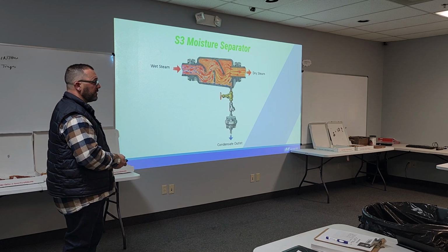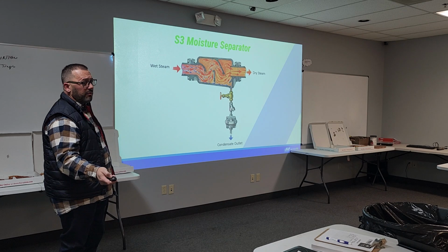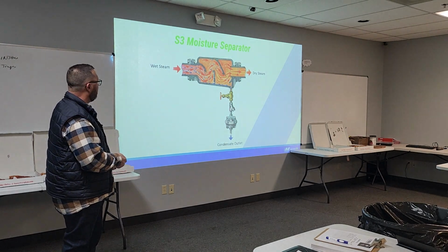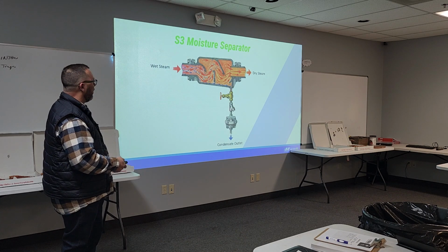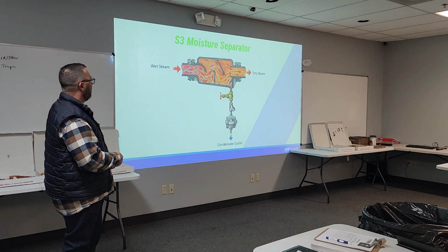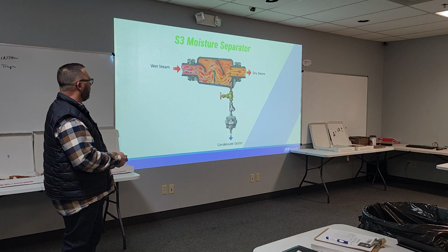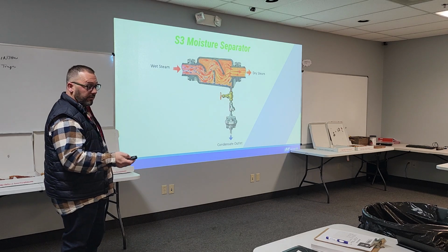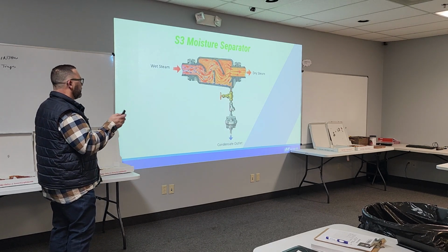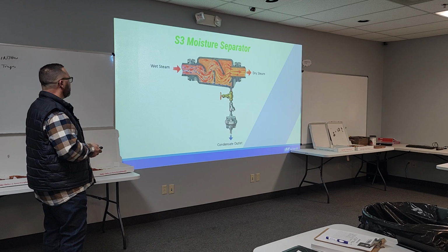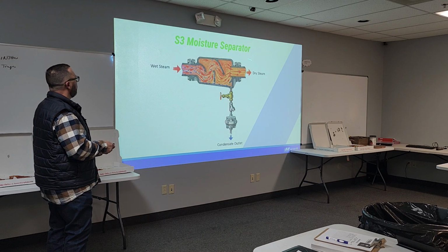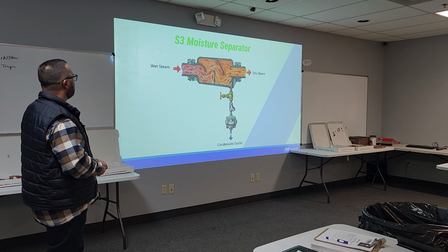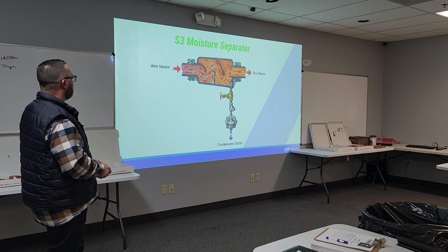And these work wonderfully on compressed air. That's the other thing people miss, that everybody's got wet air. These babies work, and airlines are small, 1/2 inch, 3/4 inch, 1 inch, so the separators are very inexpensive at that point. When you get into the 3, 4, and 6 inch, I've sold a 24-inch separator before, those get very expensive. We could talk for hours about that, but we're not going to. These are wonderful and certainly worth their weight. There's no maintenance really associated with these guys at all.